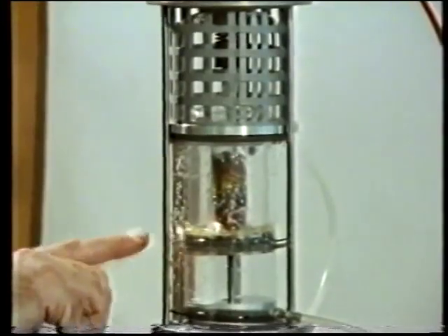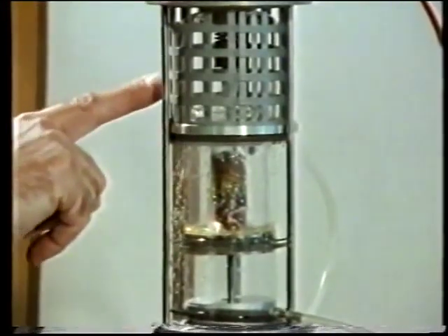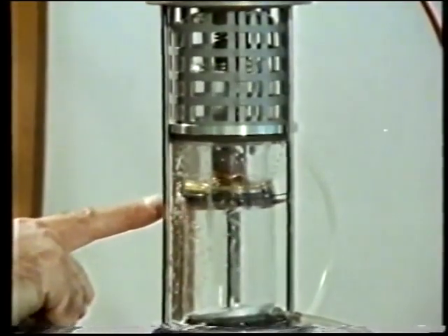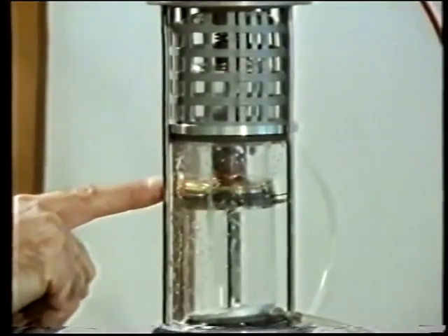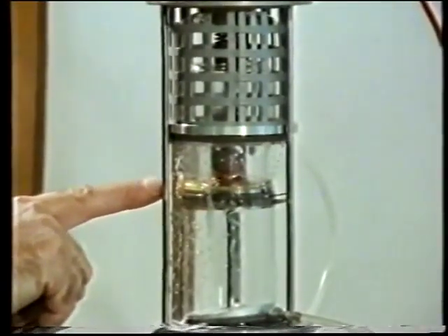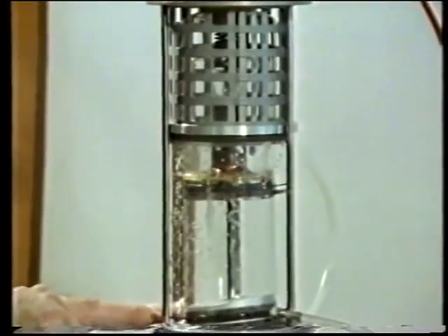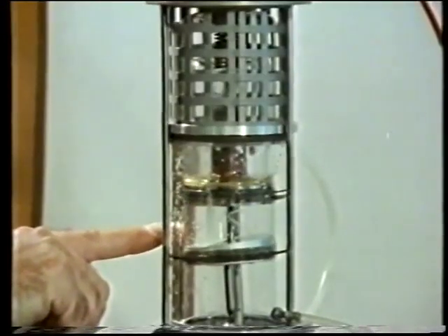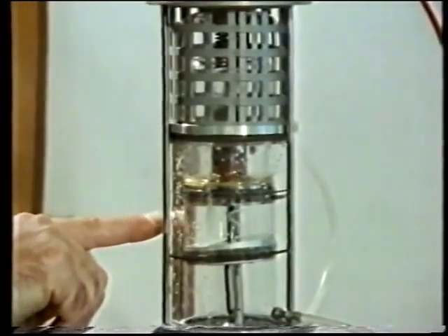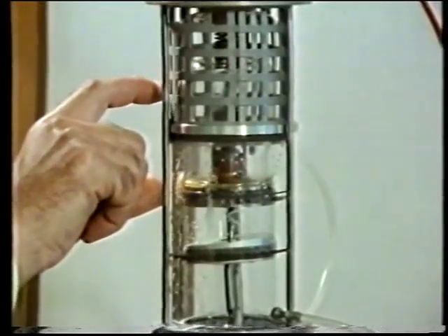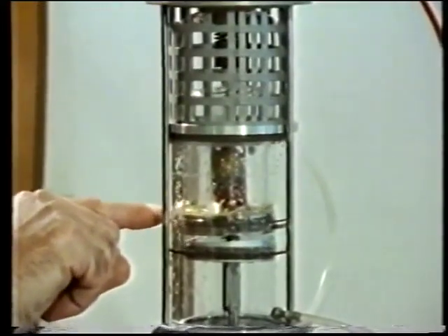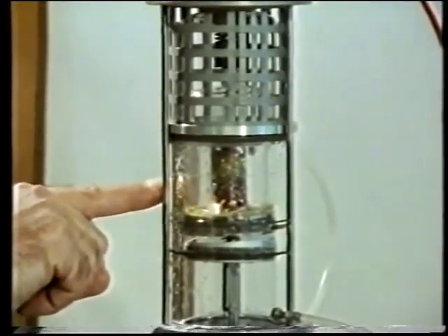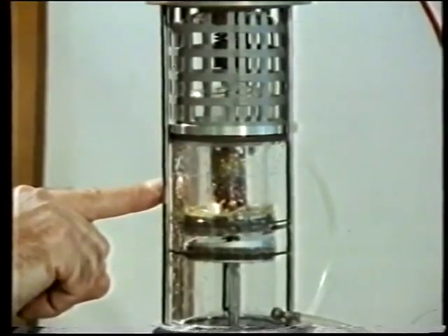At the end of the power stroke, the gas is displaced from the hot side to the cold side by movement of the displacer piston. The gas gives up heat to the regenerator during this process. The upward movement of the piston causes the gas in the cold space to be compressed. At the end of the compression process, the displacer moves downwards to push the gas back to the hot space. The gas picks up heat from the regenerator during this process to complete the cycle.